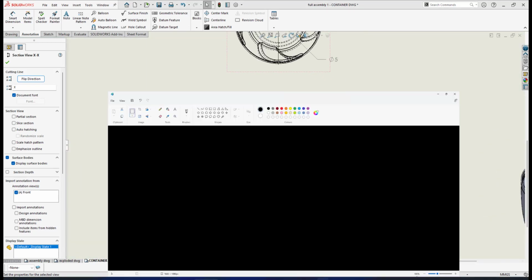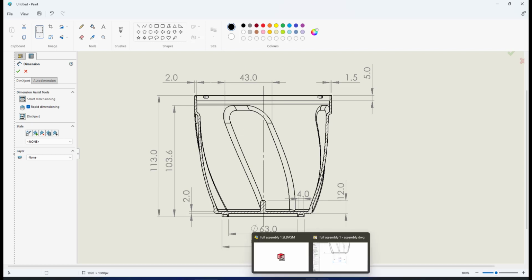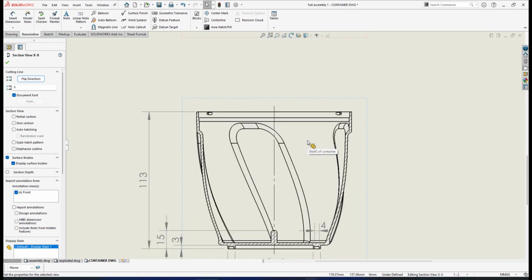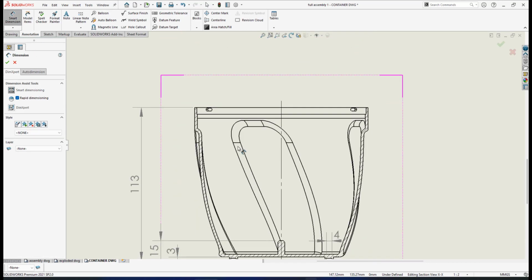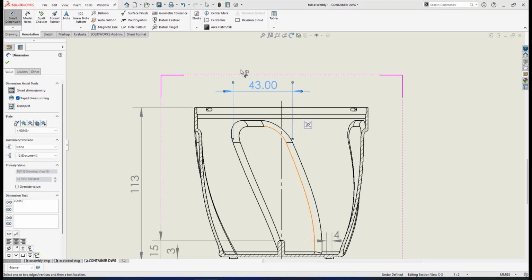Okay, another thing is about the dimension on this top part here. So we have a groove here, by the number of 4. So at least I put a dimension about the width of this groove. Okay, hold on, I do it again. When I do the dimension of this groove, I select this point and this point. So I use the icon just now, so it puts to the appropriate level, and this one will be none, so we don't have 2 decimal points.